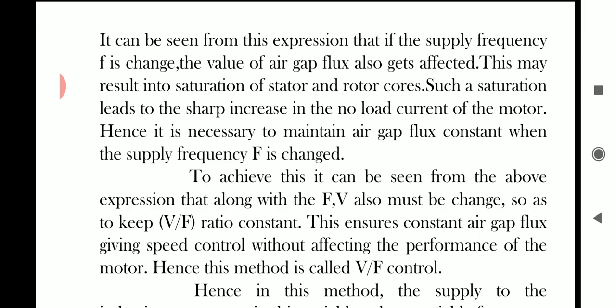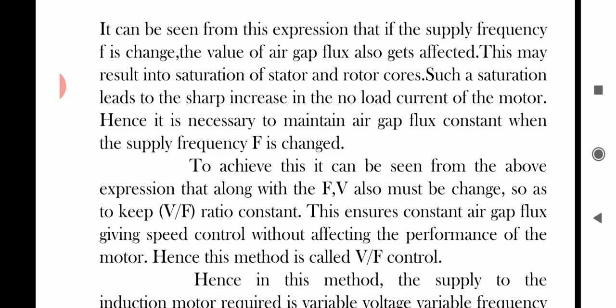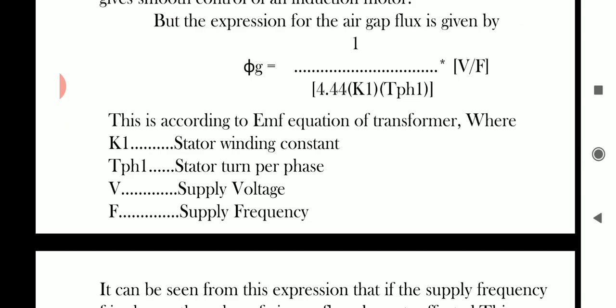As you all know, the no load current of the motor is very small, and if the no load current goes on increasing, then it will disturb the magnetic condition of the motor. Hence it is necessary to maintain the air gap flux constant when the supply frequency f is changed. It means that you have to maintain your air gap flux as a constant when you are changing the supply frequency.